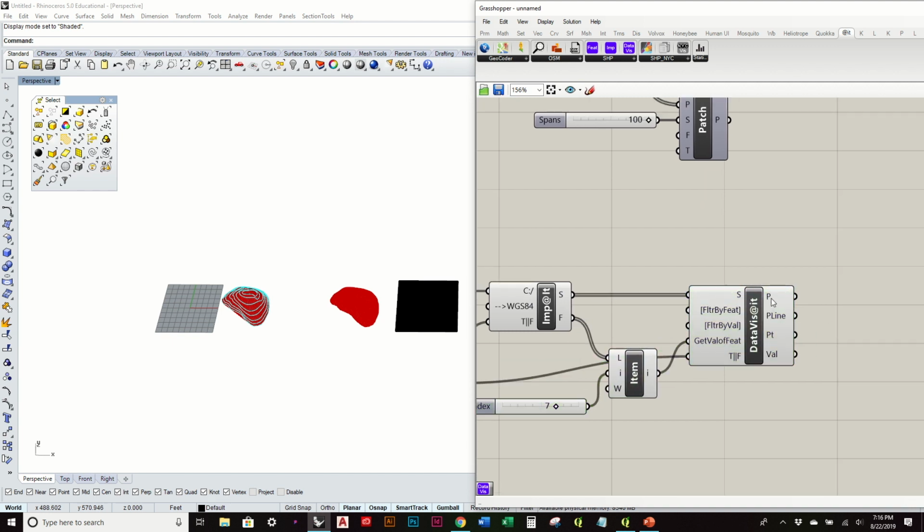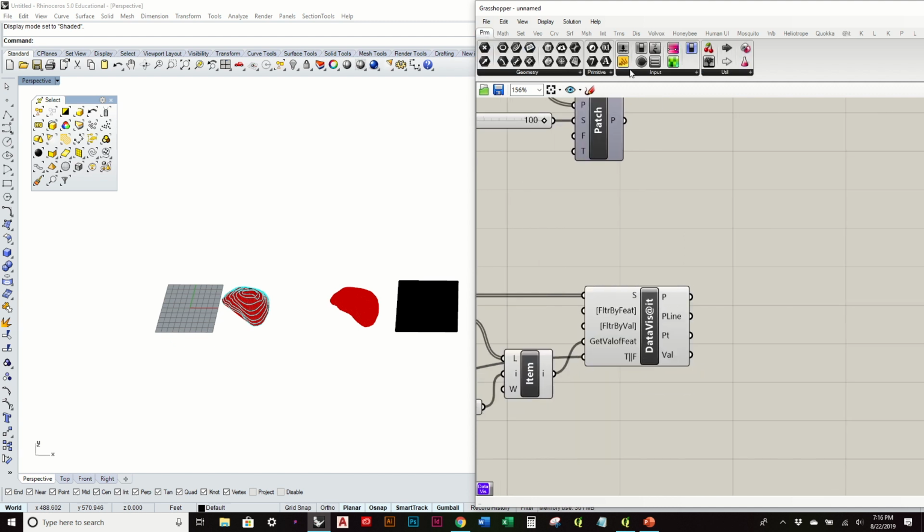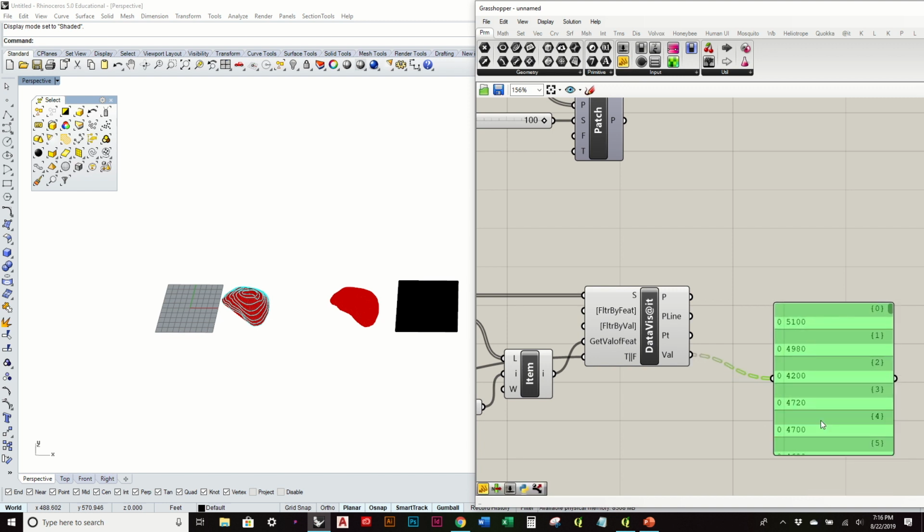But anyways, from this, it's looking at is there polygons. In this case, they're actually considered polylines. There's no points, but then there's the values, which are in fact those contour elevations, right? So I have this and I have my polyline. I can basically associate all those elevations with those curves. And you can see that there's a couple different values and then a couple different lines.